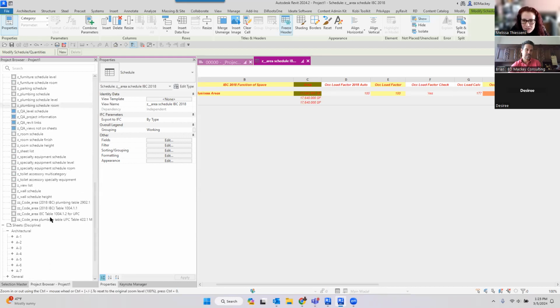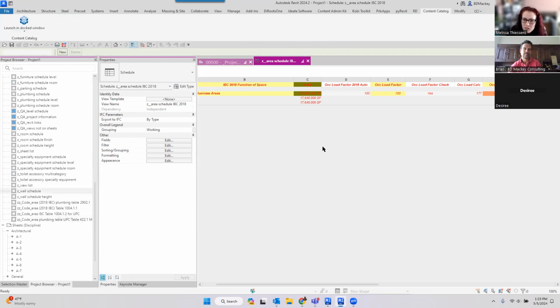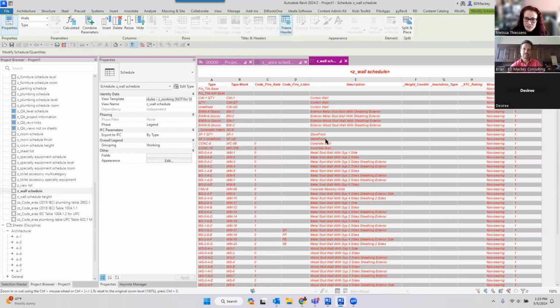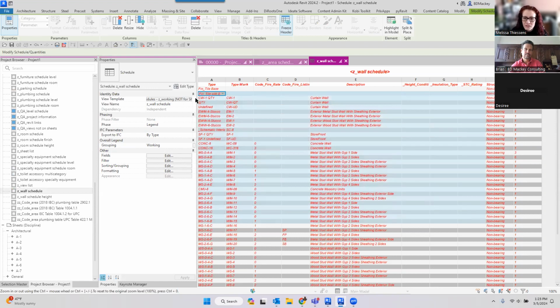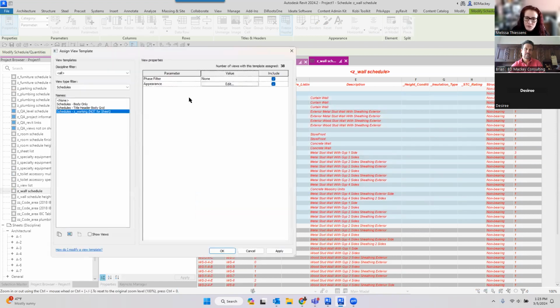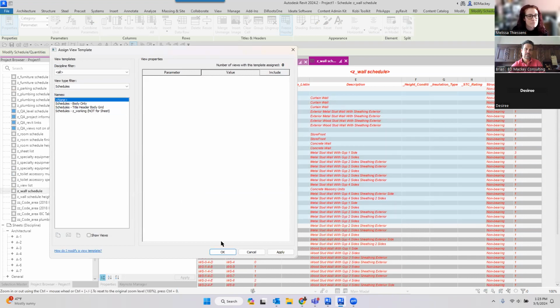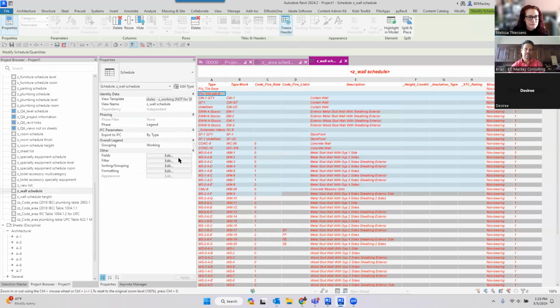Ian's comment is we have a workflow of using our template, then turning it off and changing all the text styles to our bold header style, then selecting all and turning off bold in the font button. That turns off the bold in all the text except for the headers. And that's how we get the headers to be bold. Well, wait, let me cancel this first. Then come in here and let's go to formatting. That's in a schedule. Let me go edit the view template.